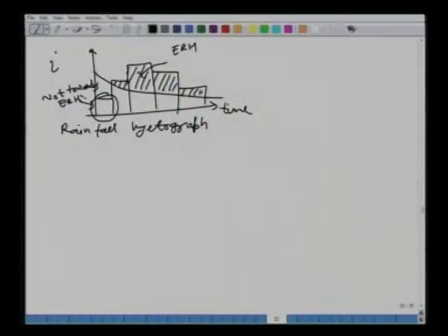So, this is the algorithm, and the next topic we will start in this chapter is we will look at another method which is also very important and very simple to use. All right. This algorithm of course is slightly complicated. One has to understand the process of infiltration, ponding cases, analyze everything and then develop this program. Okay. In practice there are some very simple methods, all right, and one of them is what is called the SCS curve number method, and that is what we are going to look at next.